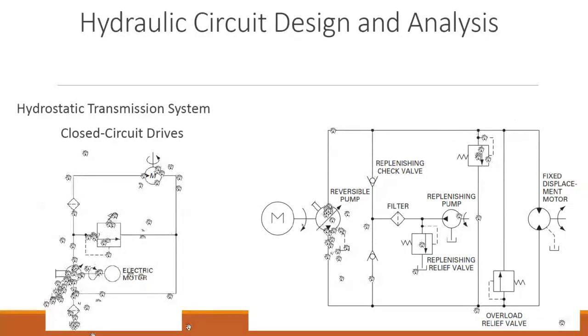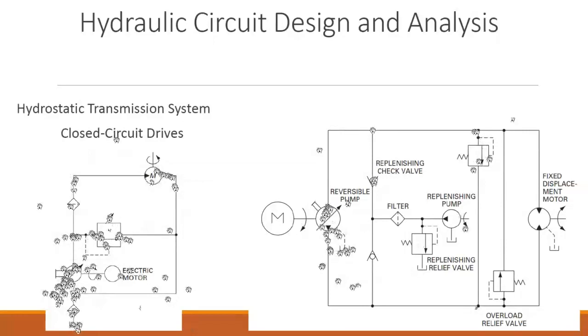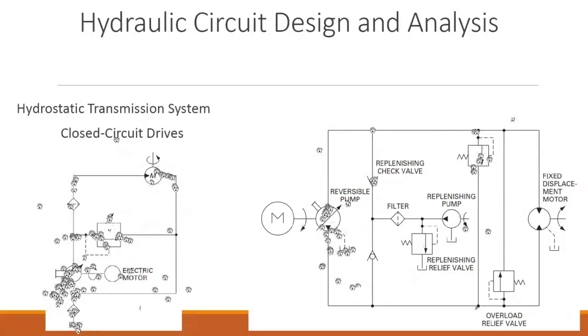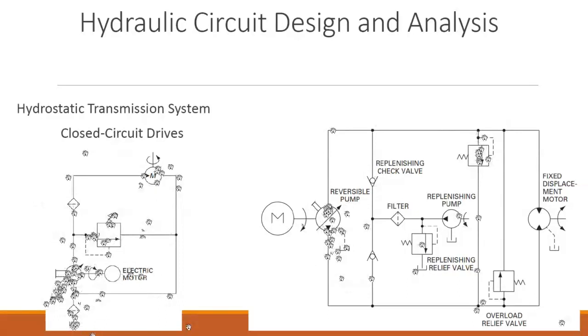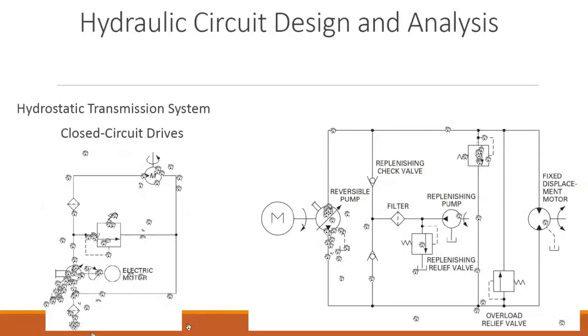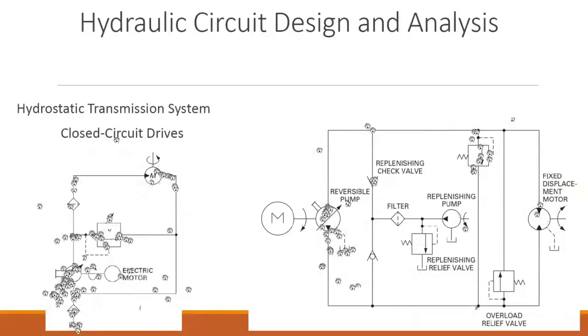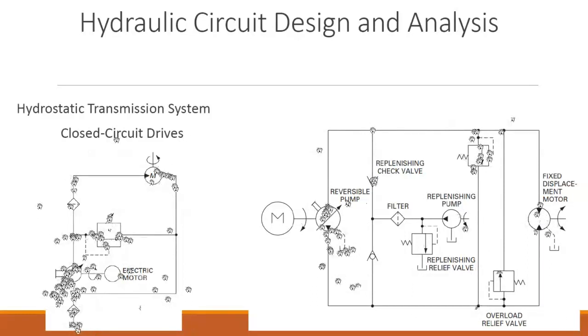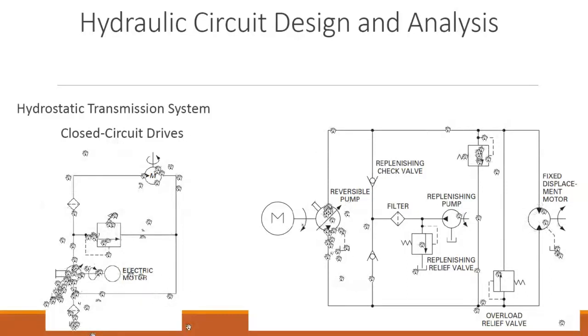Again, it tries to go through this one. Okay, again it's closed and the pressure is not enough to open this pressure relief valve, so nothing would happen. It's not exactly a pressure relief valve because it is not giving off the oil to the tank, but it is just there to go through this one so that the motor can be saved. So it means that if the pressure is excessive, this will open and the oil will not go to the motor and will save the motor. Okay, the oil will just continue circulating like this. So it is closed, it is closed, the oil goes further, comes here again, it is closed, goes here, does the work in the hydraulic motor, and then if there is any leakage, that can be seen here